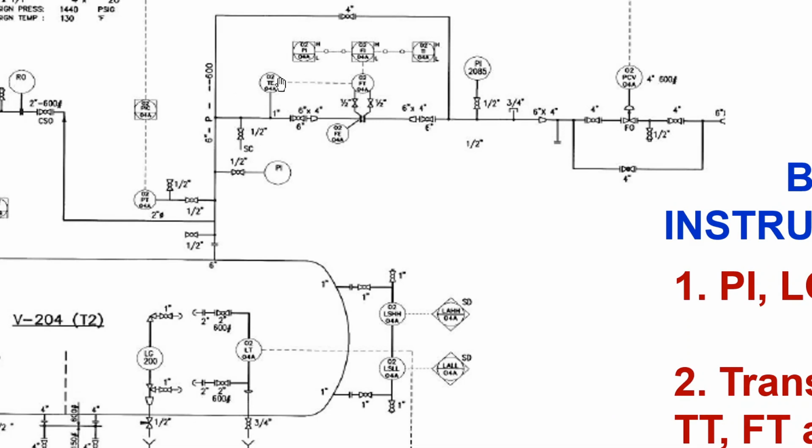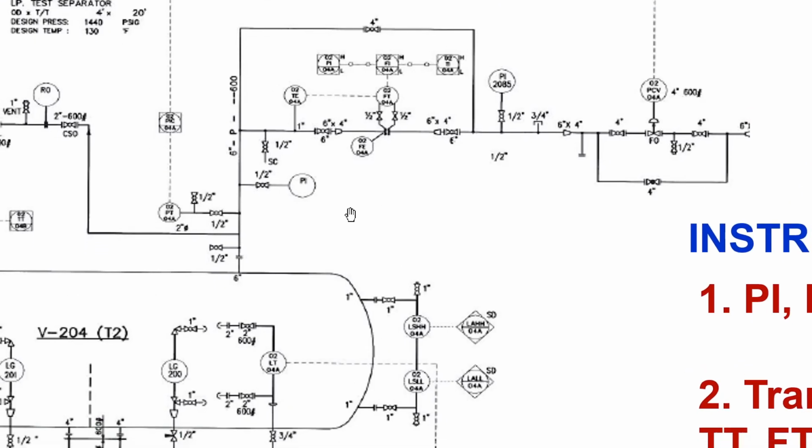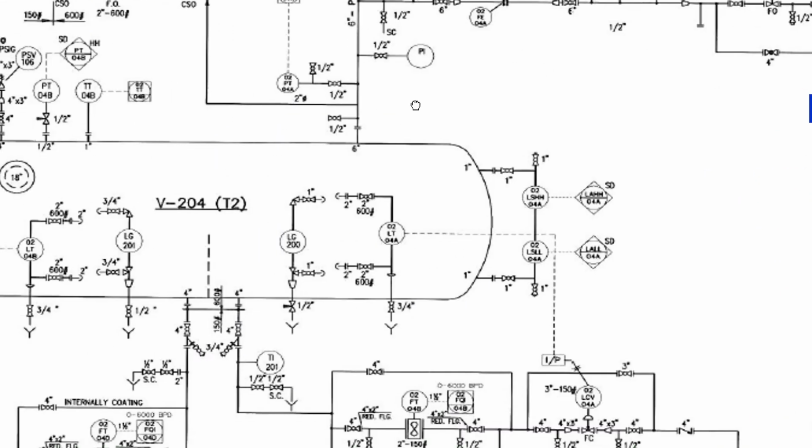Going to the next one, this is the flow transmitter with a flow orifice plate. Upstream of the orifice plate there is a pressure indicator, and downstream there is also a pressure indicator. In case some differential pressure is forming, he can identify that as well. This control system we will discuss at a later stage. So there are two pressure indicators, and these are field instruments.